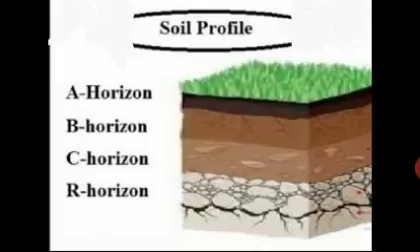First one is color. Color is one of the most useful and important characteristics of soil identification. Color of the soil depends upon its composition, drainage condition, porosity and age. Concentration of organic matter imparts a gray, black or dark brown color to the soil. Diffusion of iron oxides imparts red and yellow color to the soil. Manganese dioxide and hydrated iron oxides may also contribute red color.